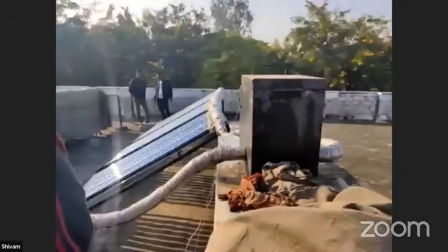Actually, this is the evacuated tube. This is an insulated tank. It is used to heat the transfer fluid in the solar collector. The fluid is filled into this tank and circulated in a closed loop using this gear pump. We get hot fluid at a temperature of about 150 or 160 degrees Celsius at the outlet, and we can use this fluid for any heating application like solar water heating, solar air heating, or solar drying, using any suitable heating system. We are using this for air conditioning purposes.